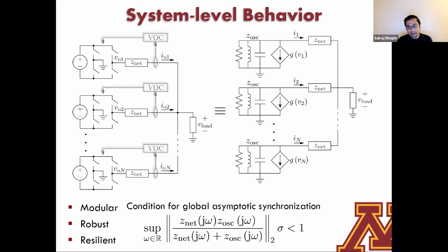And again, I use this term in a very specific manner. Why do I call it robust? That's entirely because the load does not show up anywhere in this condition for synchronization. So the load could be linear, nonlinear, and it could exhibit quite complex behaviors in its own right. We'll see that in some of the experiments that I outline in forthcoming slides. But again, the load does not show up, and so it is robust to what's happening on the load side.